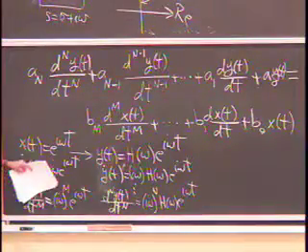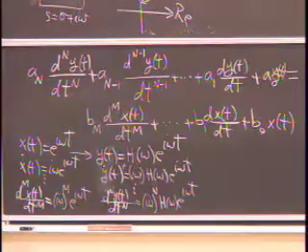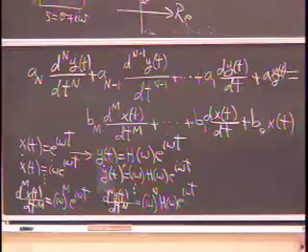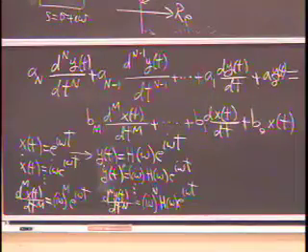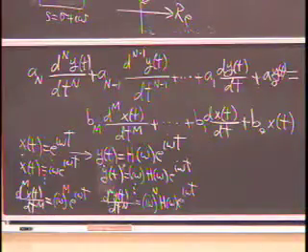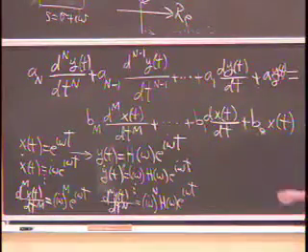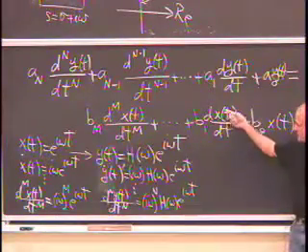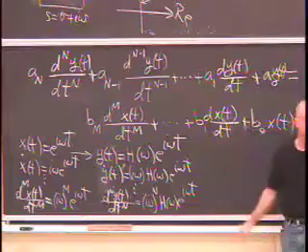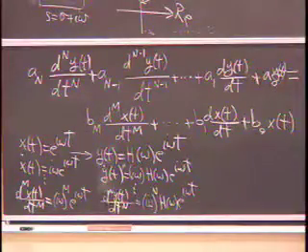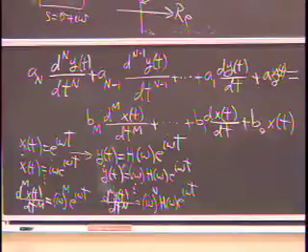Now I want you to plug these into that differential equation. Don't bog yourself down with the math. It should be fairly easy because of the pattern. And tell me what the H of omega is for this system. You have all the coefficients. These are assumed to be known. And you now have expressions for each of these derivatives. So just write it out and tell me what H of omega is in terms of a ratio of a polynomial in I omega over another polynomial in I omega.